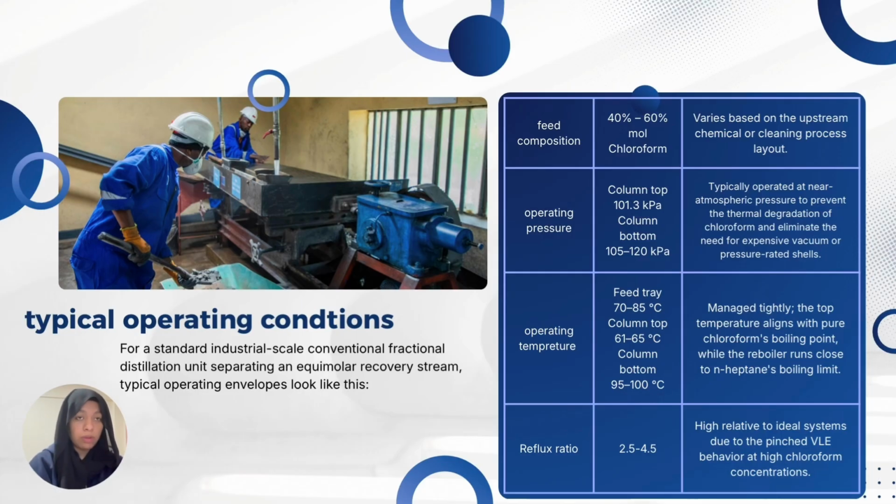The reflux ratio would be between 2.5 and 4.5, which is high relative to ideal systems due to the pinched VLE behavior at high chloroform concentrations.